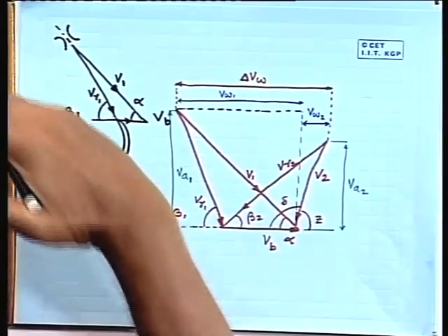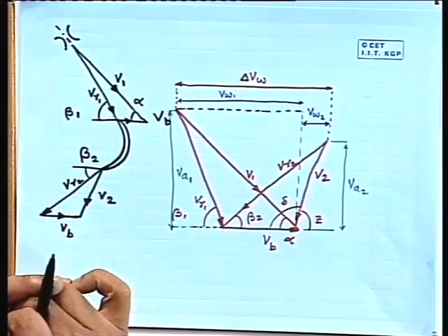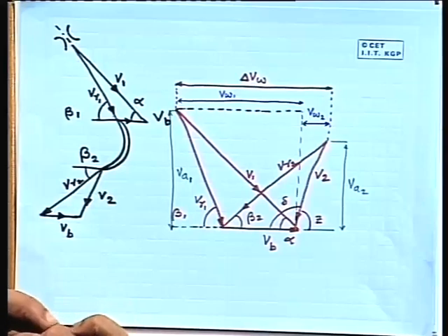It will be very slant then, and the blade passage will be very obscured. There are some limitations. So, generally this angle is kept 12 degree, 14 degree like that. We generally do not go to a smaller angle than 12 degree or 14 degree, 16 degree like this.